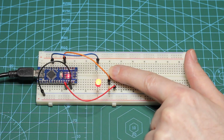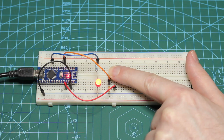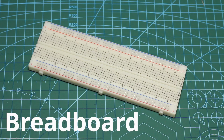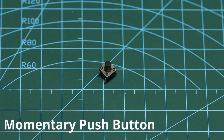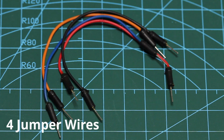Today, we are going to look at how to use a button to turn an LED on and off with an Arduino. For this tutorial, you will need an Arduino, a breadboard, one LED, one 240 ohm resistor, one momentary push button, one 10k ohm resistor, and 4 jumper wires.